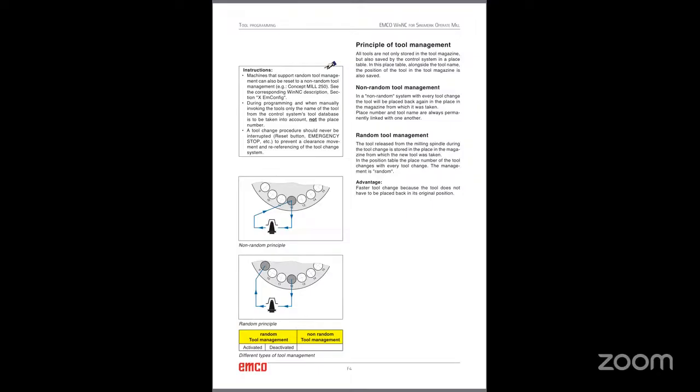So before running a program, the suggestion is to open the tool list and check the tool diameter, tool radius, cutting number, spindle direction, coolant setting, magazine place, etc. If you set a tool wrongly, then it will create machining size error, tool breakage, and a collision will happen.